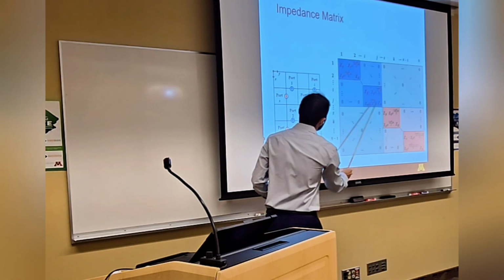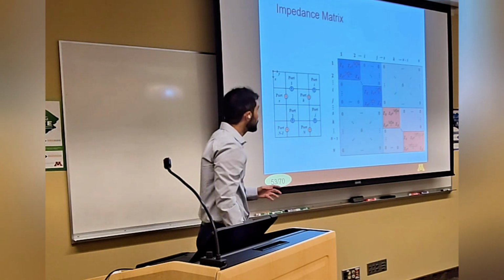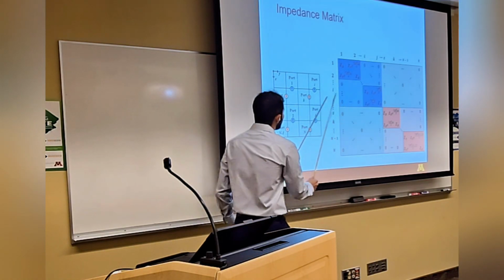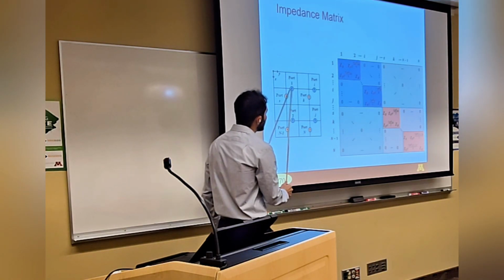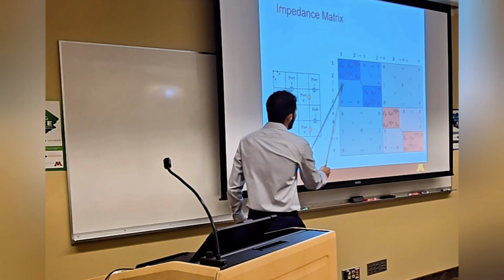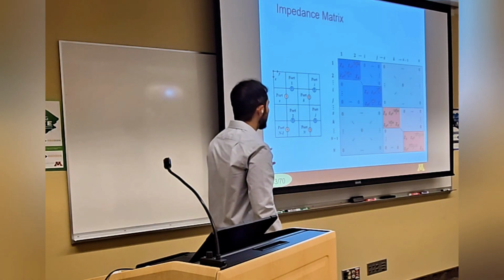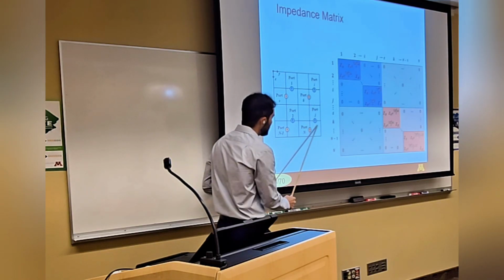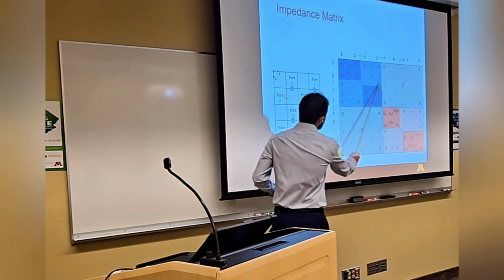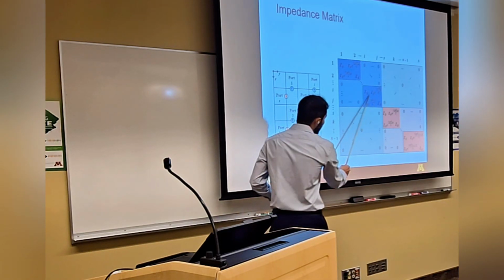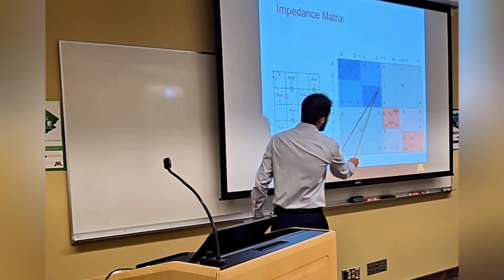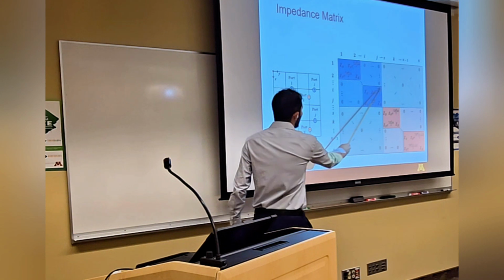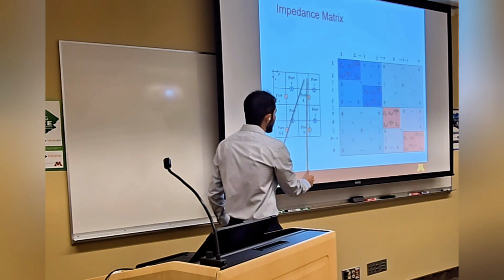The main diagonal elements are equal to the block impedance, and for those ports located in different branches, the coupling is around 0. But for those ports located in the same branch, the coupling between them can be calculated from this equation, in which alpha b is the block attenuation constant, and dij is the physical distance between two ports.